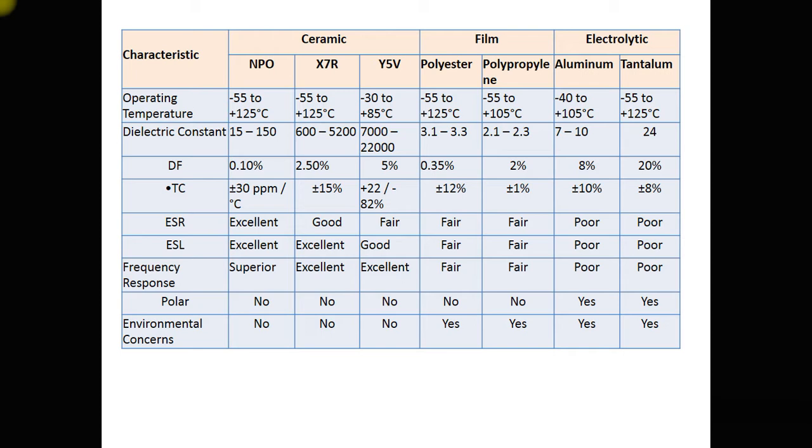Alright, so these are the various different types of capacitors that you can use over here. Just for comparison, I have given you the electrolytic also. ESR is very poor in the case of electrolytic, though these are most of the times used, but there are special designs for these types of capacitors, whereas ceramic and film types are fairly good for these applications.